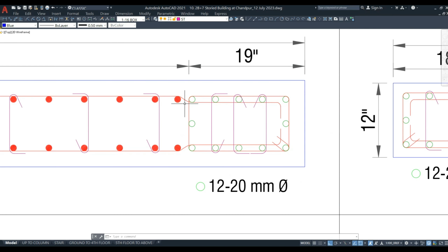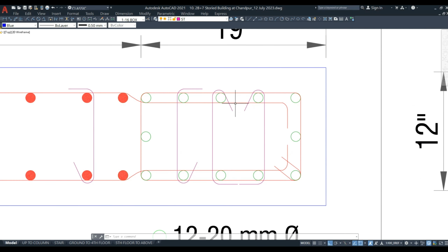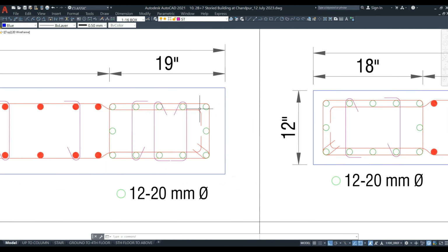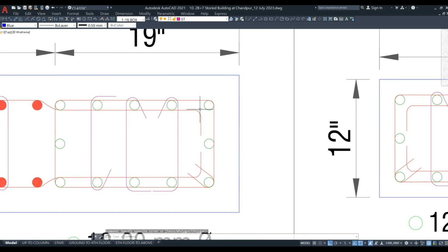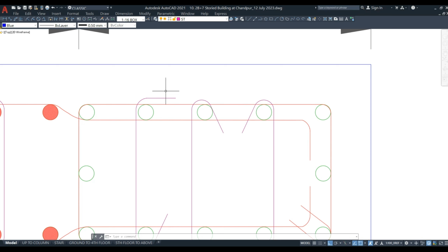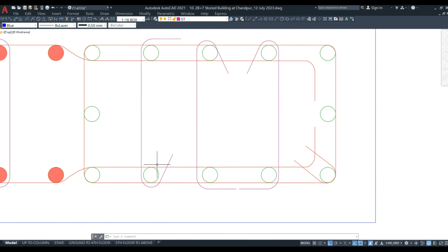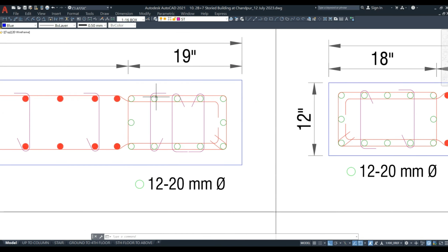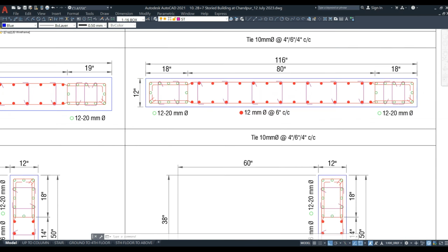Say if it is 19 inches, so it means that 16 mm bar dia requires about 30 inches of straight development length. So it indicates that straight development length is not sufficient, so you have to provide a standard hook at the end. And the code requires that the bar end should be within 6 inches from the edge of the wall. Okay. So within 6 inches, it must be located. It is automatically satisfied in our case. And of course, your hoops must satisfy the hoops detailing requirements. For example, this should be 6 dB, etc. There are other requirements which I'm not going through now.